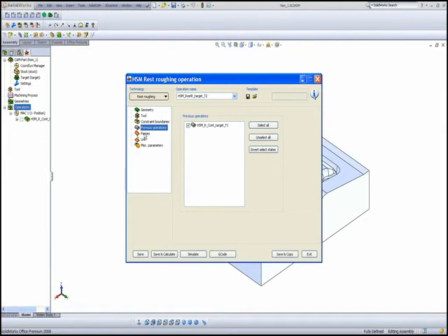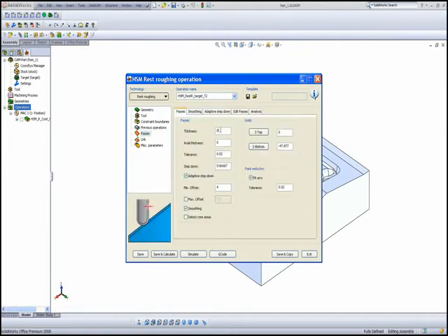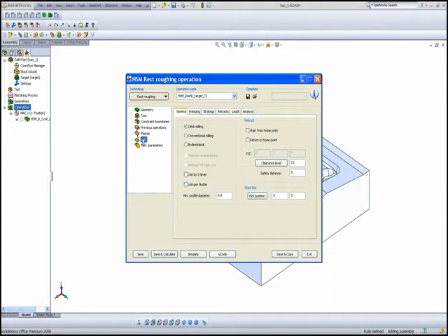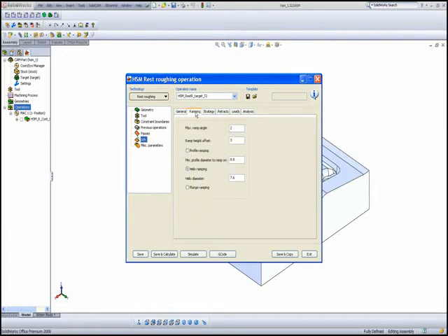field right now. Now in our passes, again, I'll be using a thickness of 0.5, but this time I step down, I'll have it at 1.5 millimeters. My link, I'll leave the exact same way it was before. My ramping, as the way I go down, this time, since in most areas there is no material left, what I'll do is I'll simply do plunge ramping.